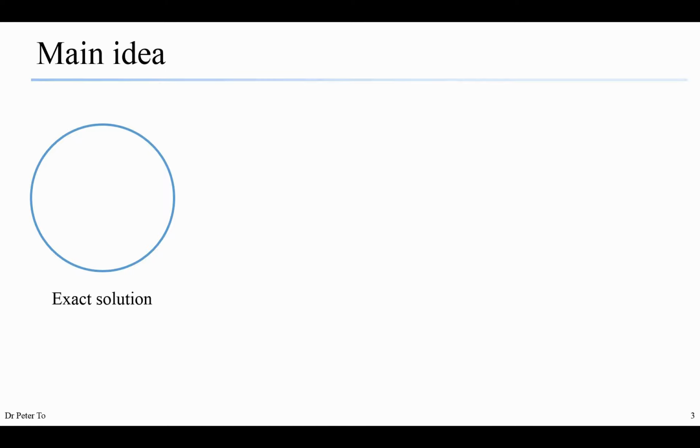There are 3 points to remind here. Firstly, displacement vectors exist only for every node in the mesh. That means we don't have a displacement vector for an element. We assume that we calculate for nodes only, and everything else will be interpolated or extrapolated later. Secondly, there is a finite number of unknowns that are required to be calculated, which will be the displacement, the force, and some other property at the nodes. And thirdly, the equations for regular element shapes and geometries are known and easily computed.